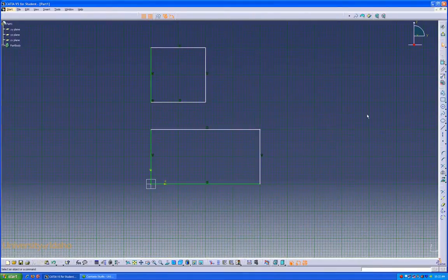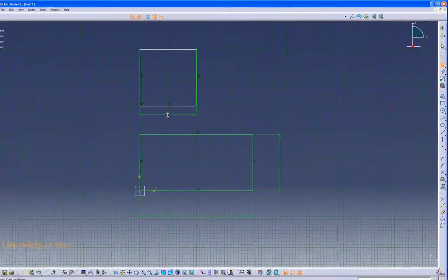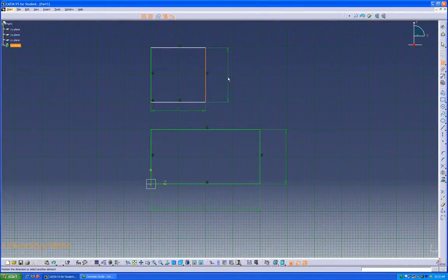To finish dimensioning these, click on the Constraint button and then click on the line you'd like dimensioned. If you'd like to dimension more than one line, double-click and you can dimension several. To get out of the double-click, either re-click the icon or press the Escape button twice.